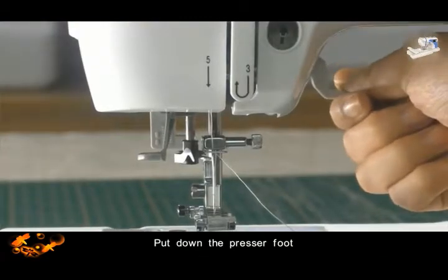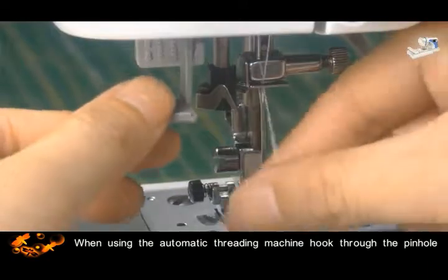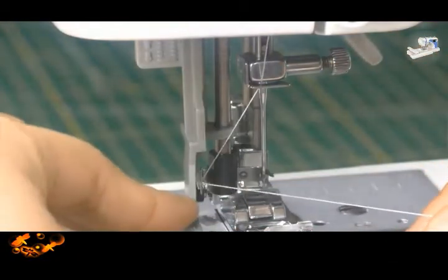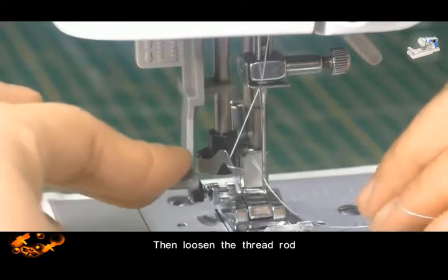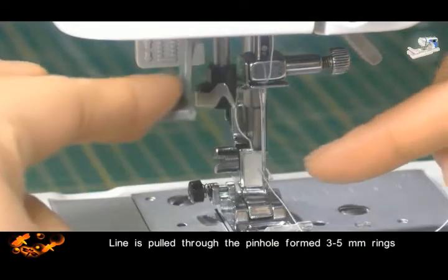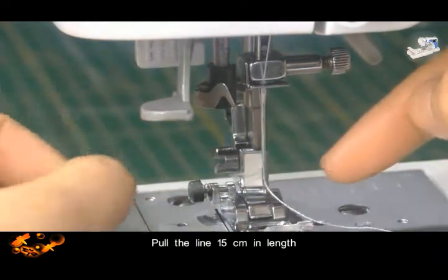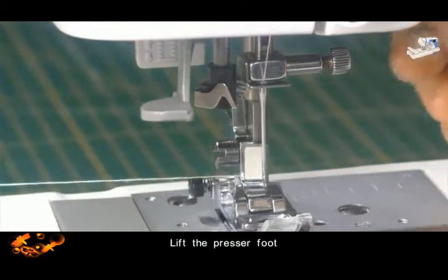Then put the thread through the needle. Put down the presser foot. When using the automatic threading machine, hook through the pinhole. Hang the thread on the hook. Then loosen the thread rod. The thread is pulled through the pinhole, forming a 3 to 5 mm ring. Pull the thread 15 cm in length. Lift the presser foot.